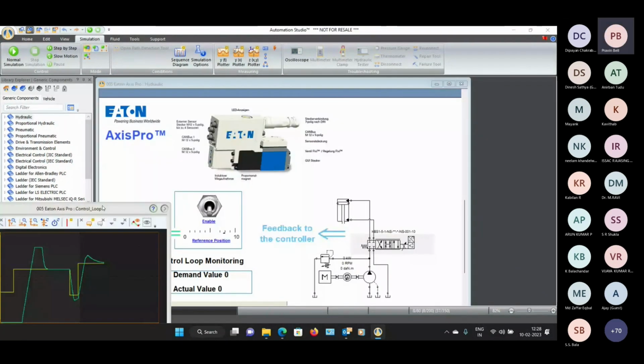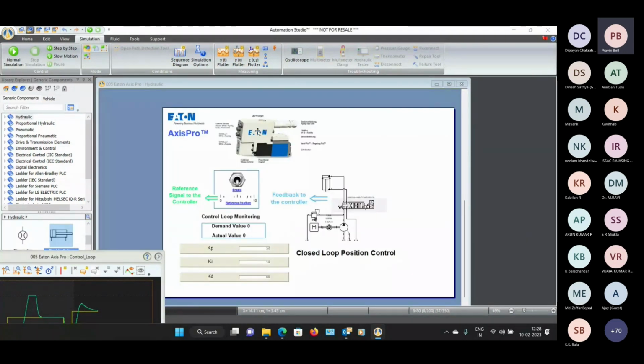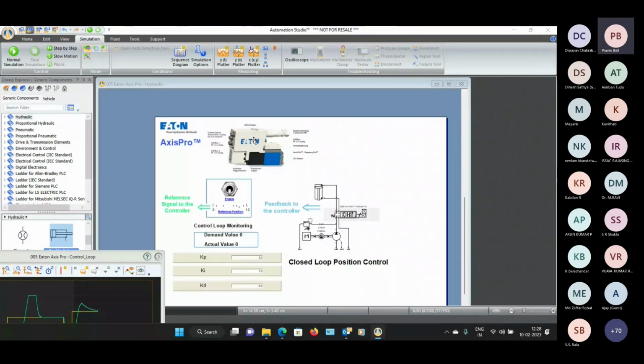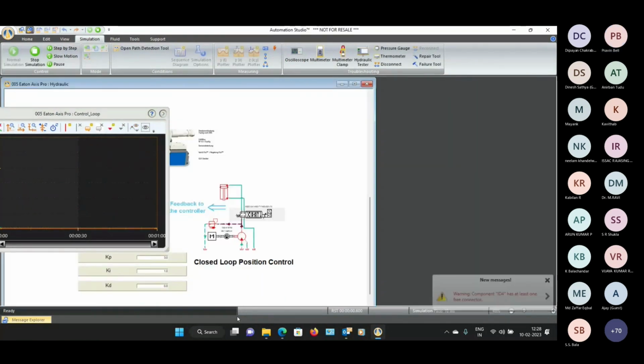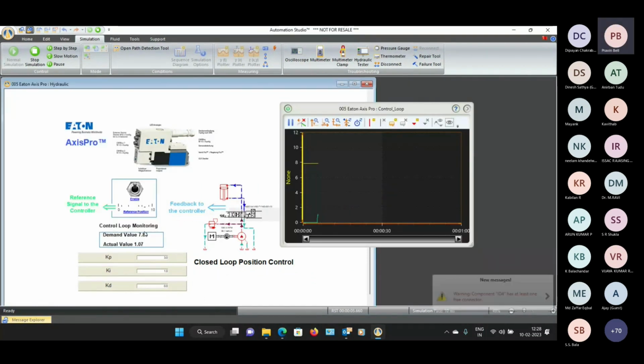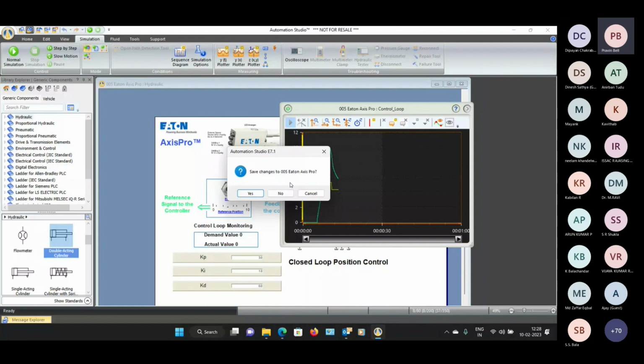Okay, this is what the valve looks like. Now, if you see these 3 inputs here, the PID online settings can be inputted into this particular valve. There's a PCB inside this particular box here. So these valves are PID based controller valves, and you can actually tune these. So this is an industry component, which is a PID based component. Okay, so these are available. It's not just theory, they are being used really widely in the real world.